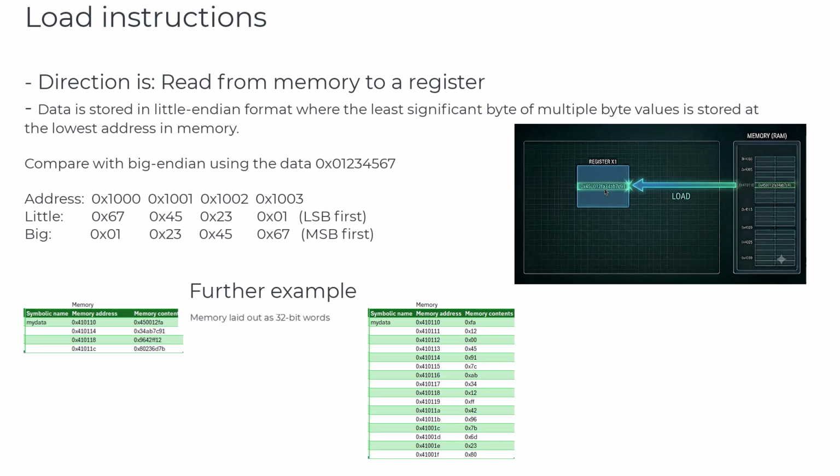But just to show you on the right-hand side, the table shows the individual bytes. Now, if we look at the memory address 41000110, it has the data FA in it. The next location has 12, so you can see here that the most significant is stored here, the least significant is here. So that's the way everything is laid out.